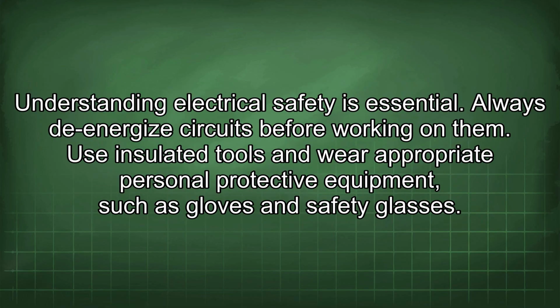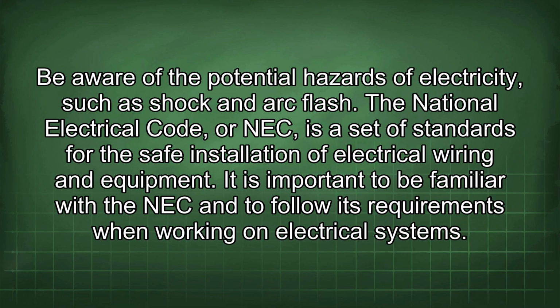Understanding electrical safety is essential. Always de-energize circuits before working on them. Use insulated tools and wear appropriate personal protective equipment, such as gloves and safety glasses. Be aware of the potential hazards of electricity, such as shock and arc flash.